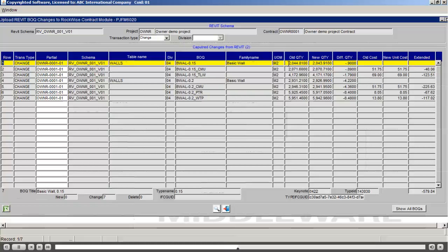Changing windows and their sizes also changes the walls around them, so the system tracks up to the slightest millimeter the plastering, paint or CMU changes in the wall size. Such changes are generally impossible to track to such a detail without automated 5D. All the variations quantities and their cost is thus 100% aligned with the design up to the smallest detail, and the construction manager can know directly where every single dollar goes and why. The what-you-see-is-what-you-get concept is extended to how much you pay, why and for what.